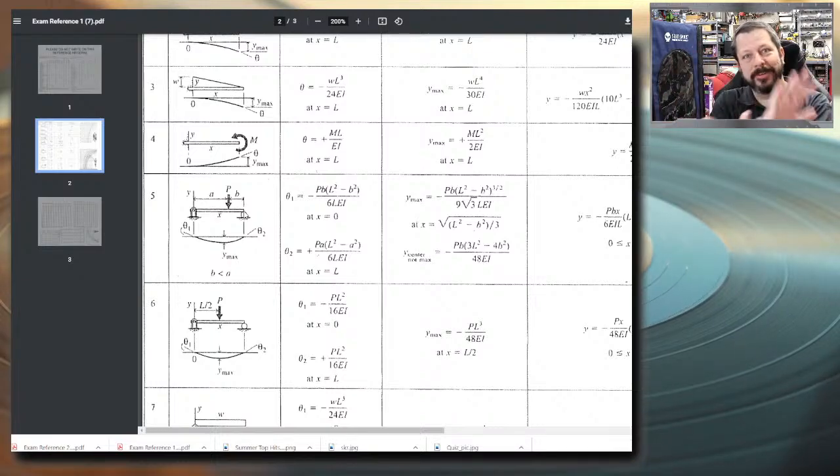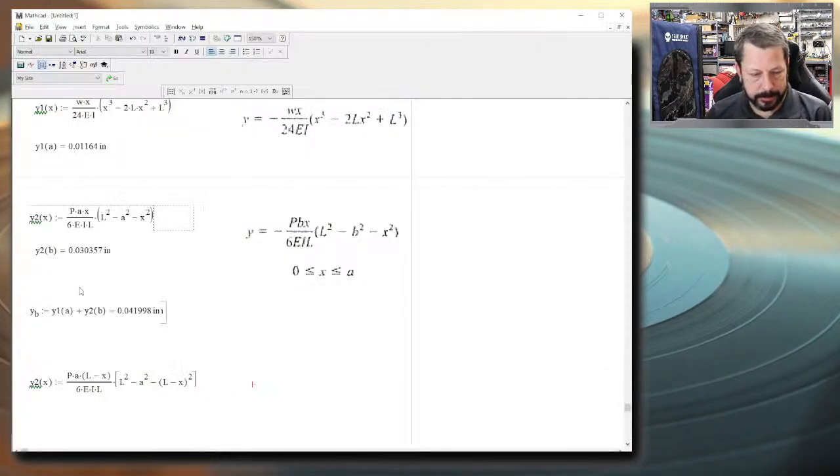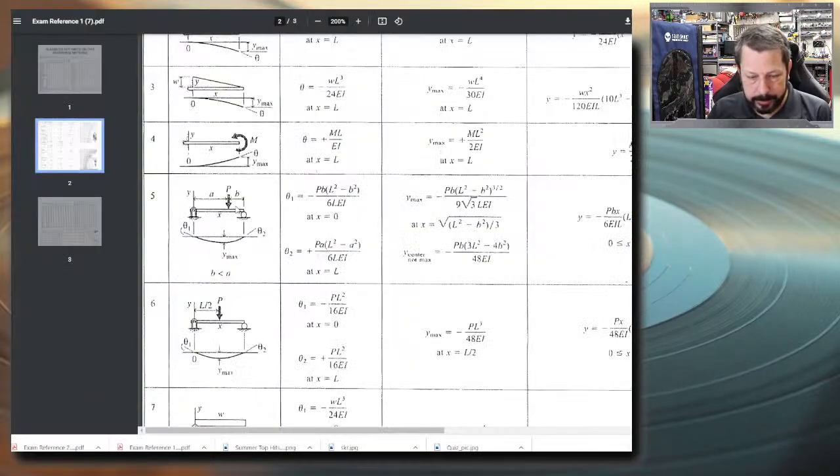But when we mirror that, that is the left end of the beam. So when we put in x equals 1, we'll have L, the whole length of the beam, 14.4 feet, minus 1, so that's 13.4 feet, which is just right over here somewhere. But when we mirror that, that's just 1 foot in from the left side of the beam.